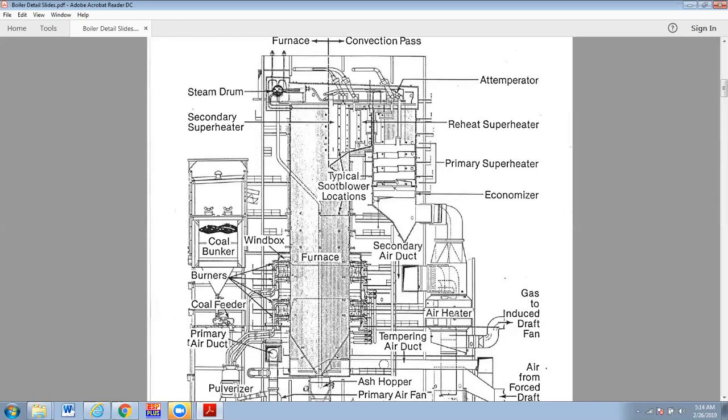You can tell it because you can't get the unit to full capacity. You can also look at the temperature drop across the air heater. So if it's not right, because some of that cold air is just leaking directly into the gas, you can also probably try to look at pressure drops downstream to see that you have much more flow coming into that ID stream than it's really designed to handle. So then, like I said, from here we go to the gas cleanup.